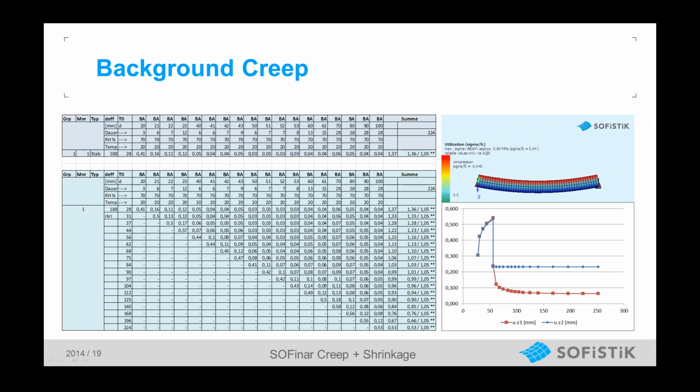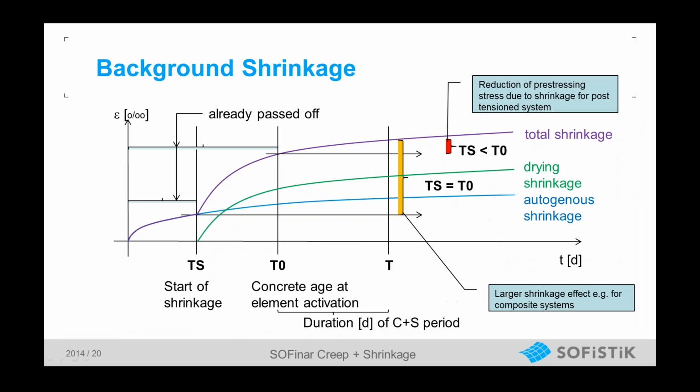So for the stress, for the force development and so on, the results are identical. So if you're interested in displacements during the erection of your building, we recommend going for the real creep evaluation. You see here in this little slide exactly what's going on.